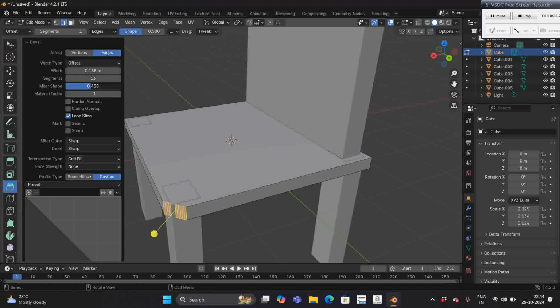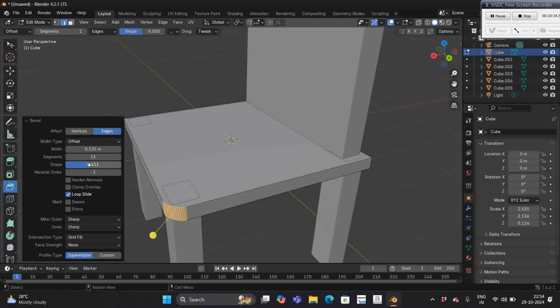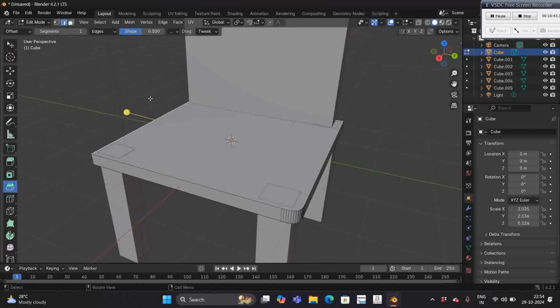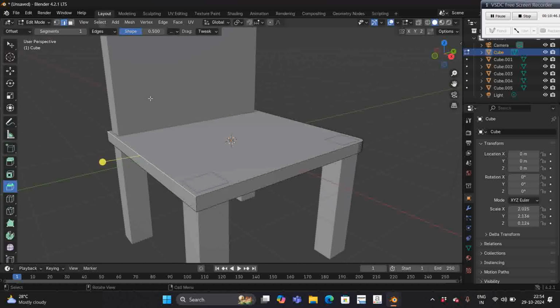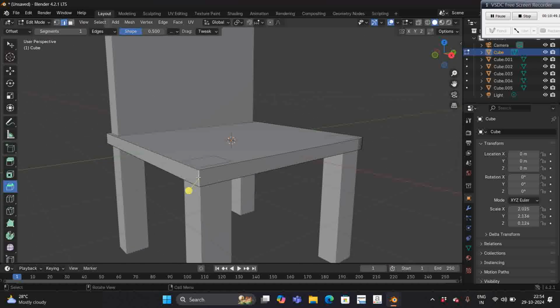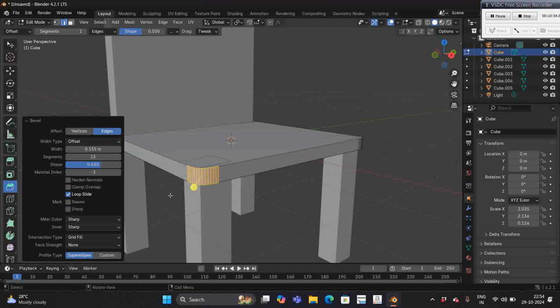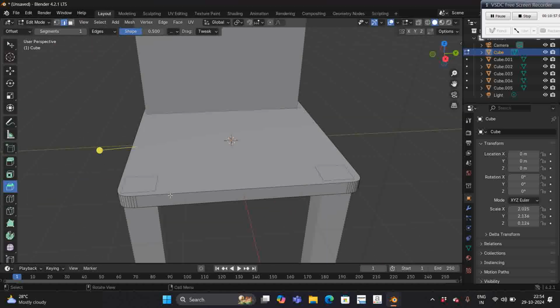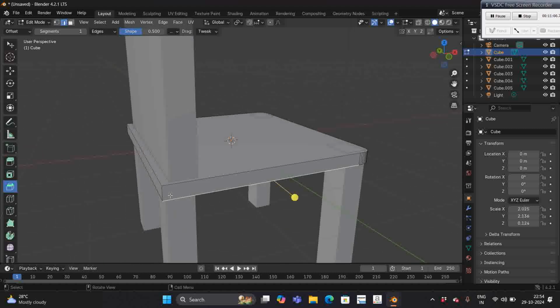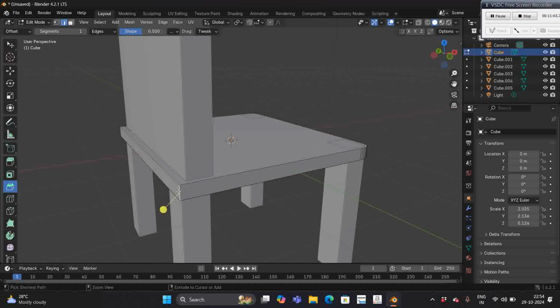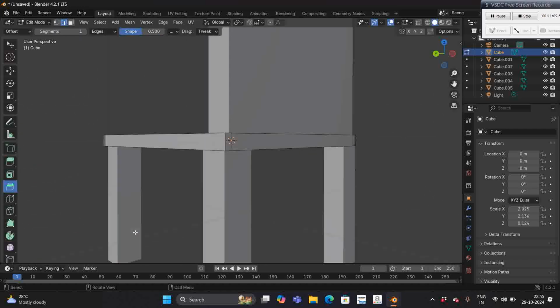After that I'll just use this shape. So supervised I have to select. You can see by changing this value I can actually change the look. So now you can see the edges are smooth, right? Same you have to do with this also. And after that, press Control B and just shape it. It is copying the previous step actually, because we have set it like that, right? Now again, Shift Control plus D we have to press and sharpen the edges like this. Same thing we can do with all the sides.